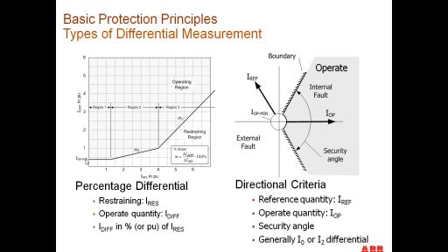So it's a very, very sensitive relay, whereas you have to set the minimum operate level on the normal percentage differential relay normally around 30% of the normal load current. You can set the minimum operate level on the negative sequence differential current at about 4% of the load current. So it's much more sensitive than the other relay was.